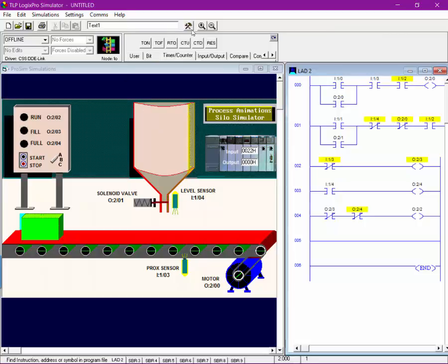But when we look at timers, we've got a time on delay, our timer number, our time base, what we preset it to, and the accumulation as it's running through the timer. We go through a particular process where we want to, say, fill up a tank with 2 or 3 fluids, agitate for 3 minutes, 2 minutes, whatever, then drain it, fill it back up, and keep going.